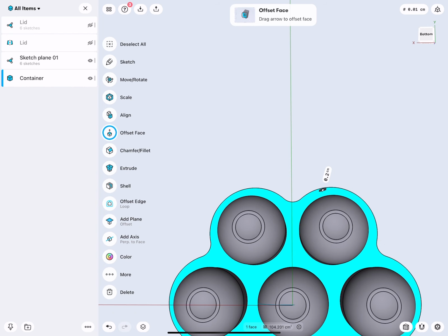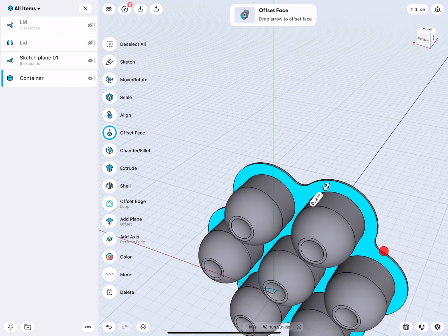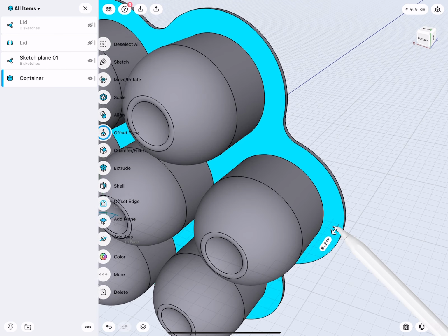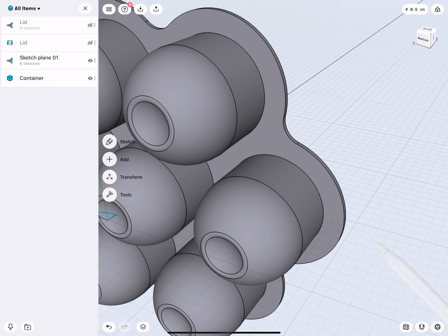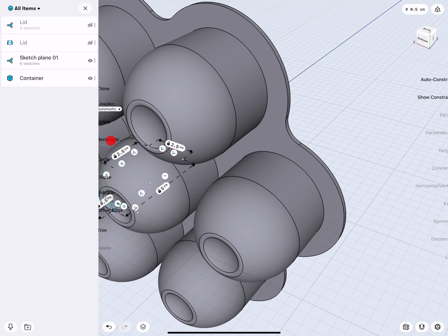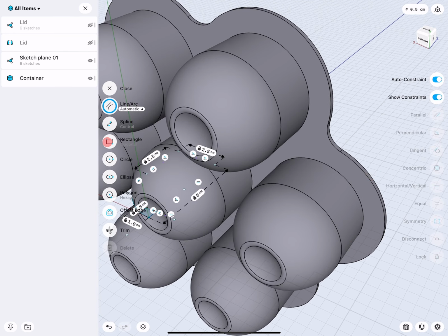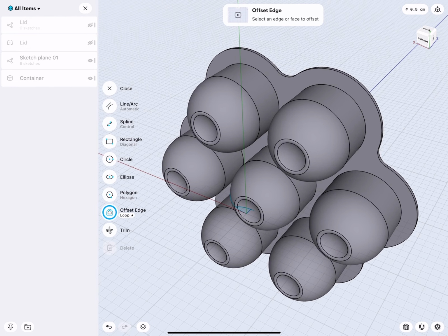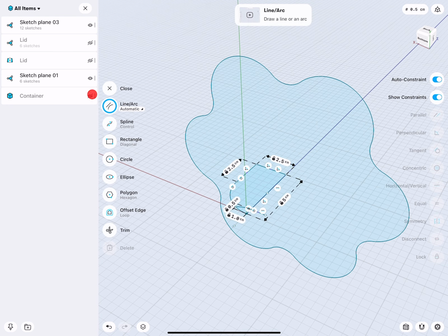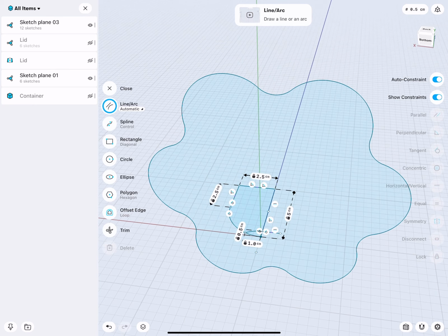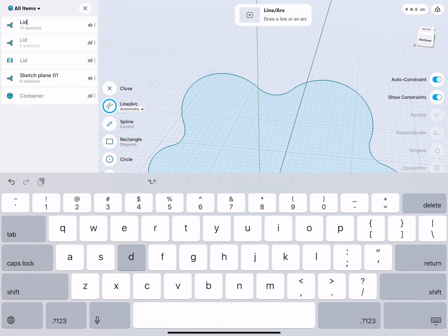The surface, because it's silicone, is very flexible. We need to stiffen everything up a little bit. So here along this edge, I would like to have something thicker. Let me show you an interesting trick. We will go to Sketch and then turn on Offset, Loop, select this edge, and then I bring this in 5 millimeters. Very good. Okay, hide this. There you see the sketch, and we will call this lid rim.